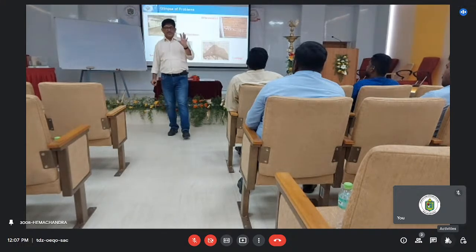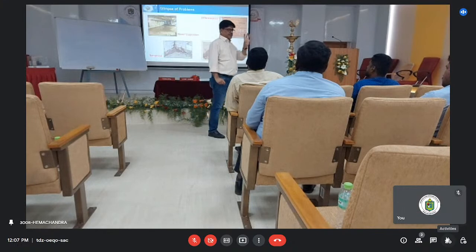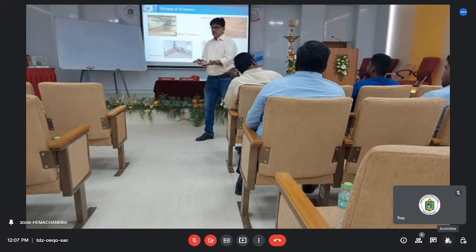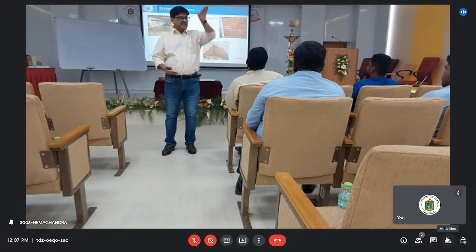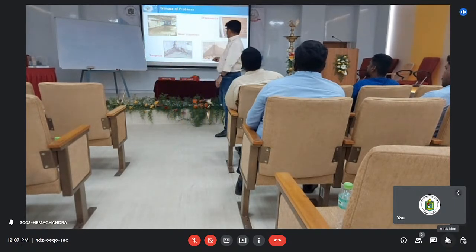These are the three sections, because we have to minimize. Whenever you are going for a cause analysis, I have to really come to a conclusion about where the water is coming from. Because if I go abruptly, I cannot check it. I have to go very slow. When I am looking at a box, one is from down, one from the corner, one from the construction joint. These are the three places the problems can happen. And the problem manifests in different ways.